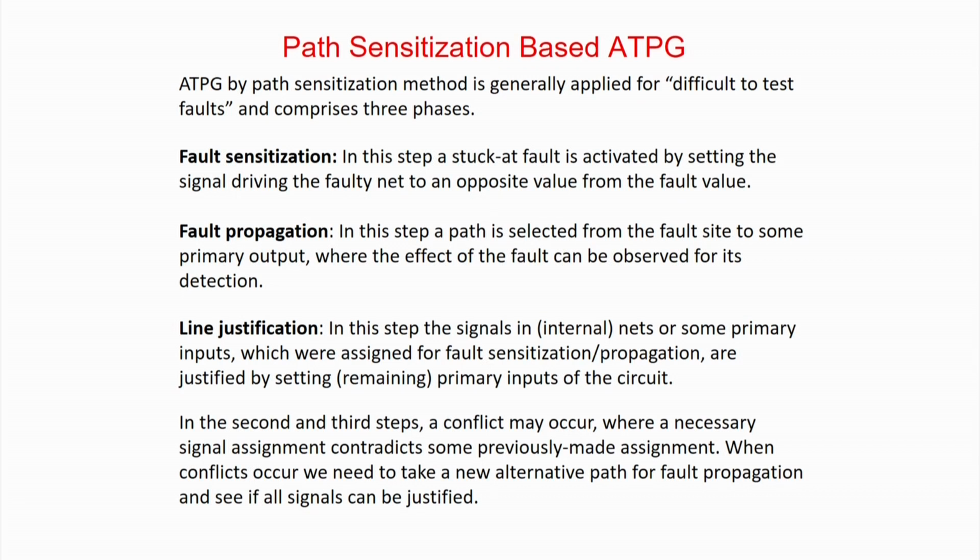In fact, the idea is that now it is not a random test. We are taking a fault, and deterministically we will find out what pattern will test it. Say there were 30 faults, I applied 20 test patterns randomly, and out of 30, 28 faults get detected, 2 faults remain. To detect these 2 faults, maybe I have to apply another 30 random patterns, because they are difficult to test faults and may be detected by only a single test pattern, and that pattern has to come in random fashion. So the probability is less.